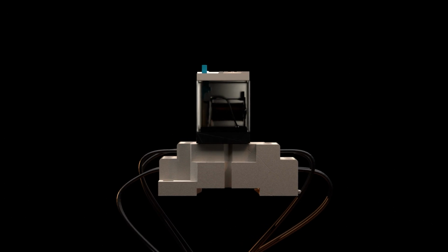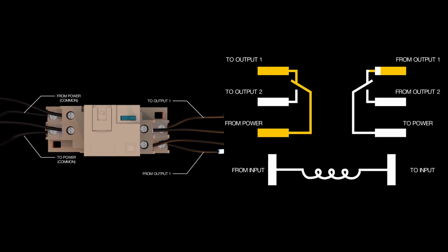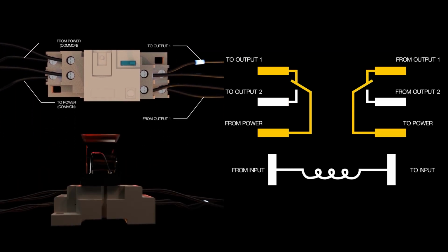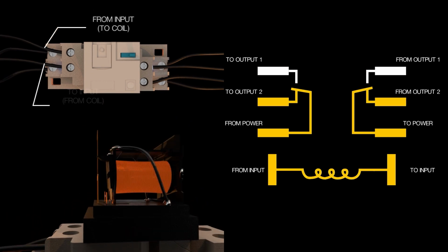First, we will be discussing how the control relays work. Control relays are electromagnetic switches that, when power is applied to the coil, turn on the electromagnet, pulling a conductive fork from one side of the contacts to the other, turning one internal circuit from open to closed and another one from closed to open.